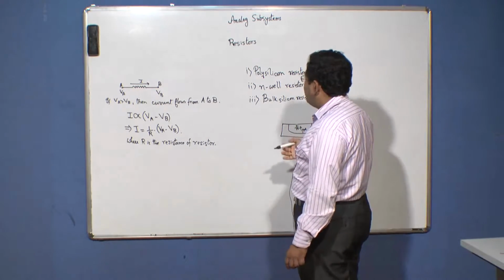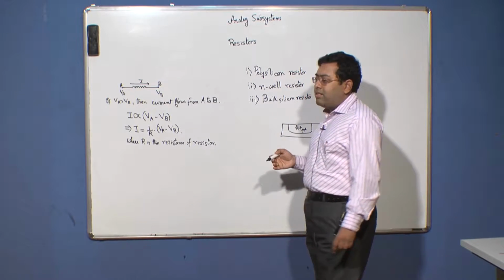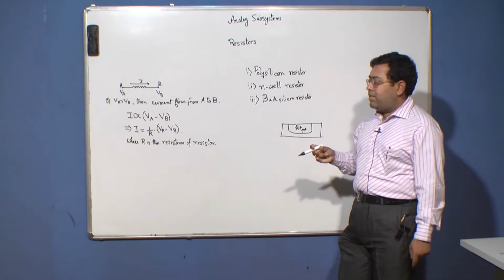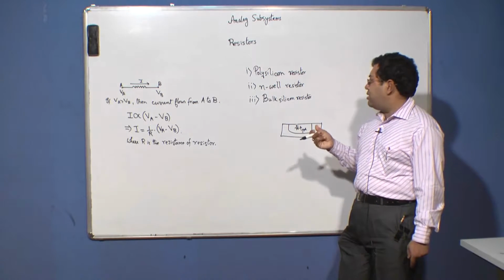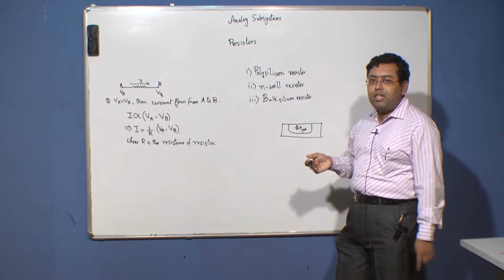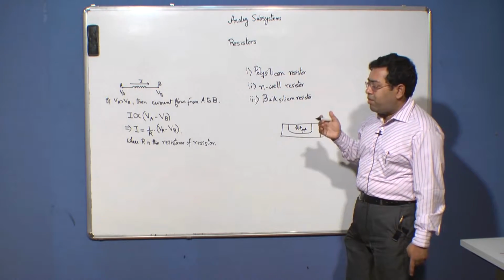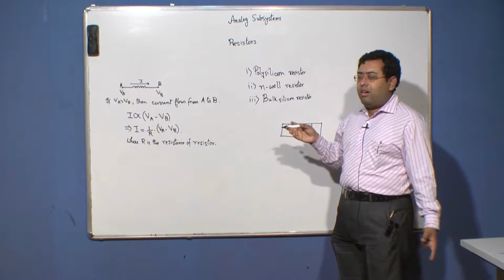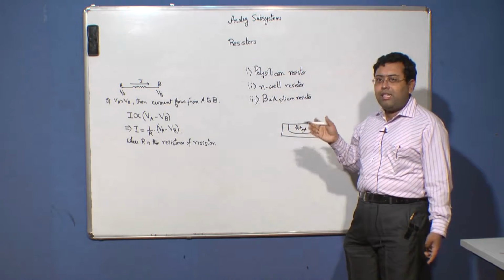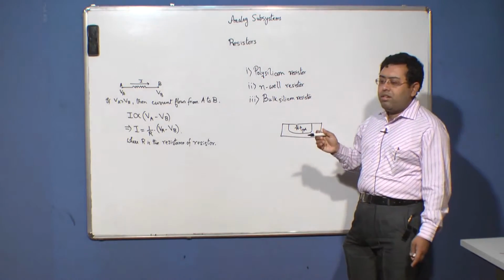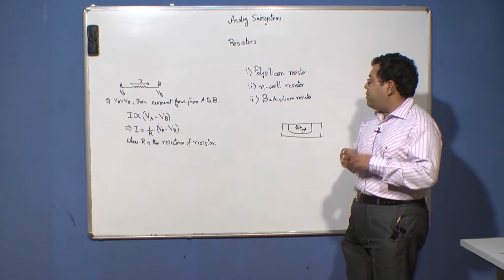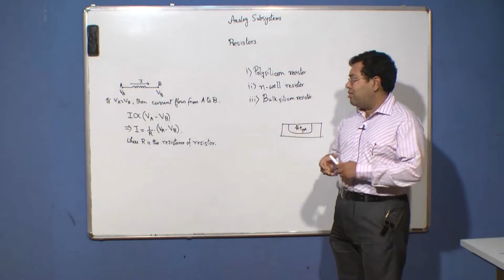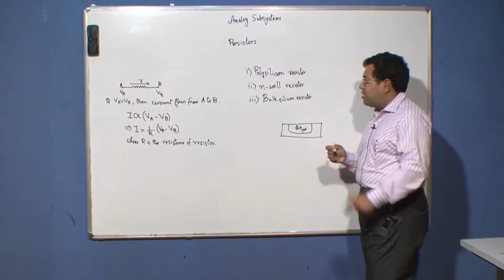The other way is you can use a polysilicon resistor, where the resistance is much less, and typically for moderate range resistors we use a polysilicon resistor. But for all these resistors, what we really end up with is a fairly large area of the IC being consumed by these resistors. So, in practical cases we seldom use these passive resistances; we basically use MOS resistances.